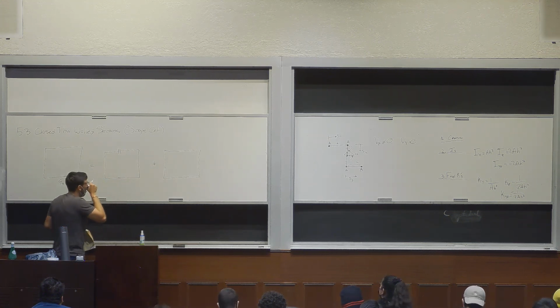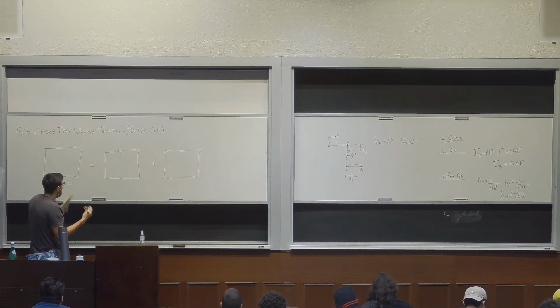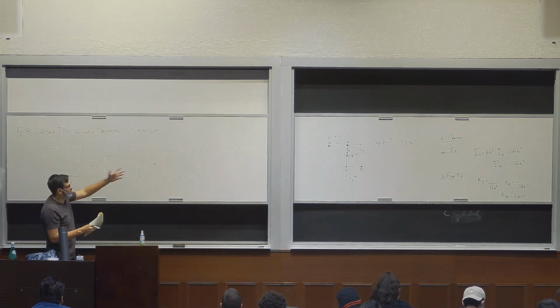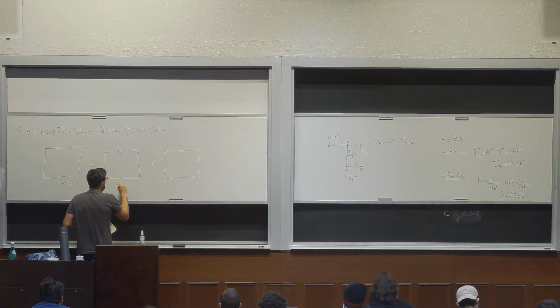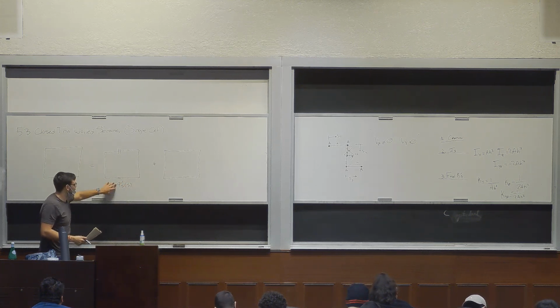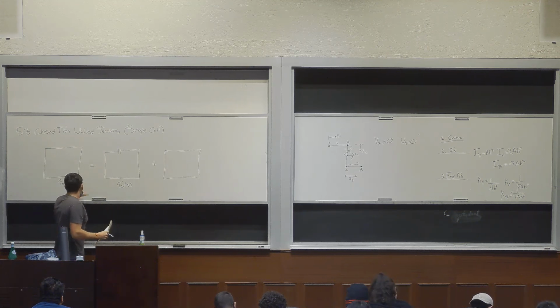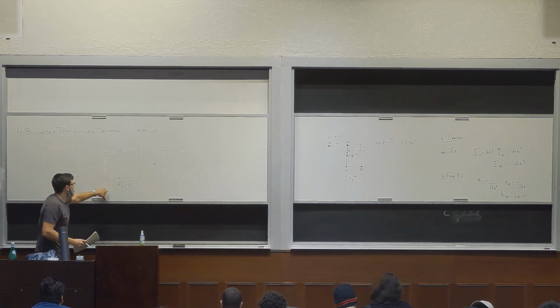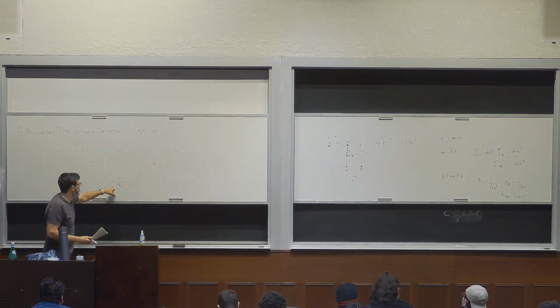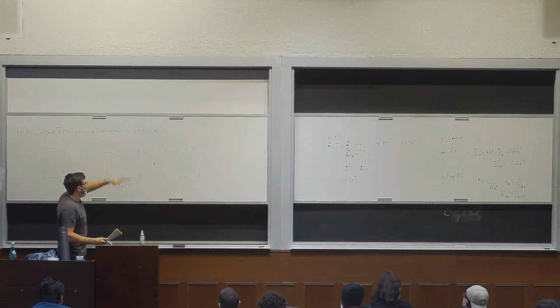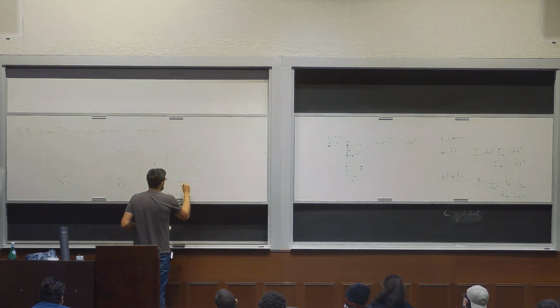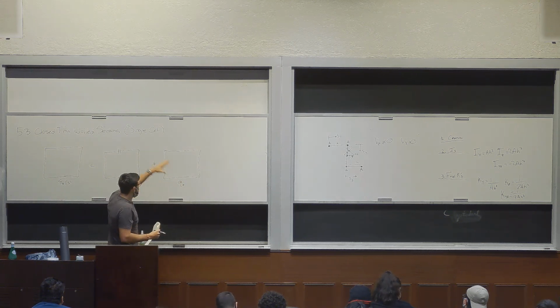You can choose whatever location you want. And you can solve that. We just talked about how you solve that. We start at an open end and you continue. Simple as that. So that'll give you QS prime as it varies with S. We'll call that QS prime. However, that, of course, is not that. So there's a difference between this and this. Basically what you're missing when you solve this is the shear flow that would have occurred here that you got rid of by making that cut. And that shear flow is constant throughout the entire section, and we're going to call it a constant Q naught. So that's constant throughout the whole thing.